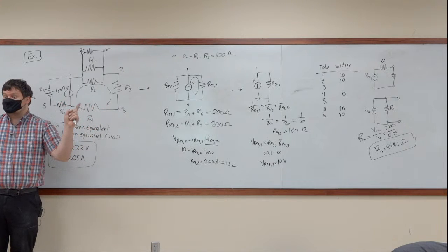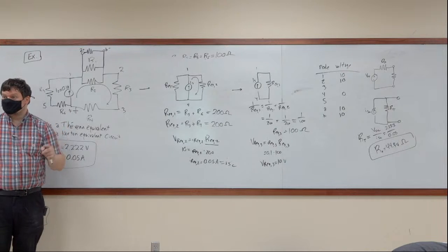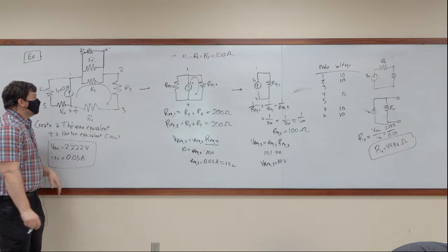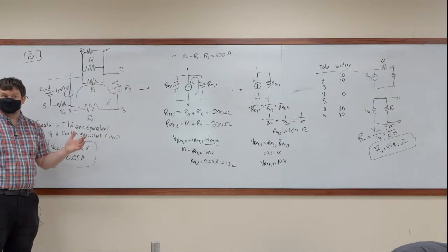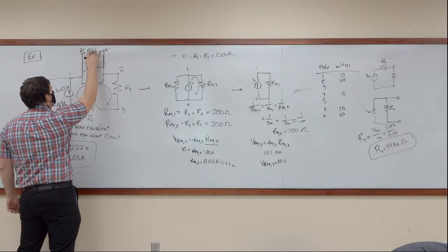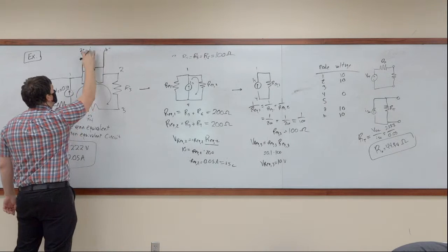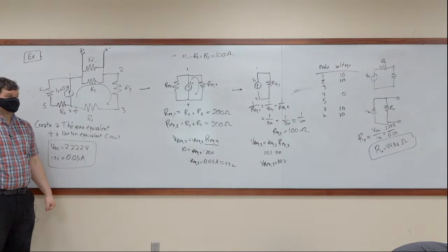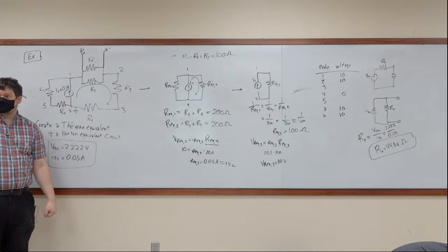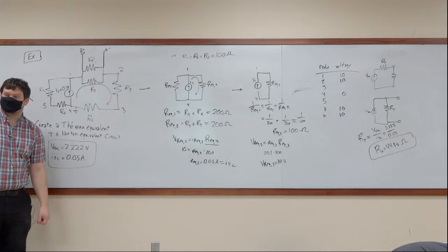This is 10 million times easier, okay? Because you take a really, really high value resistance, which by the way is included in a voltmeter. You just touch the voltmeter to A and B when it's open. Done. You now know what the open circuit voltage is. You didn't have to calculate anything.